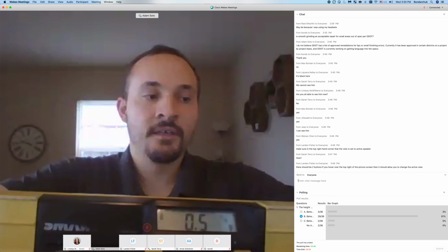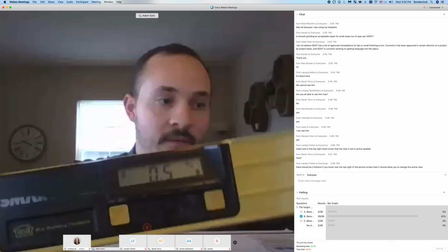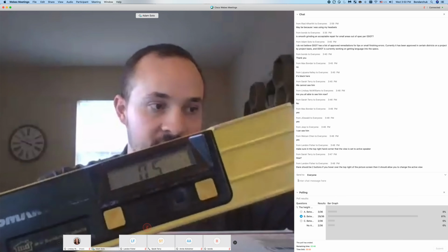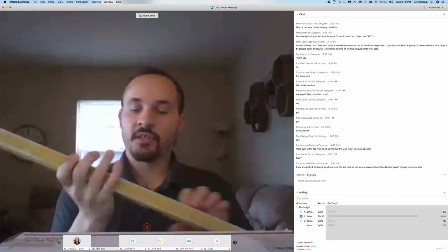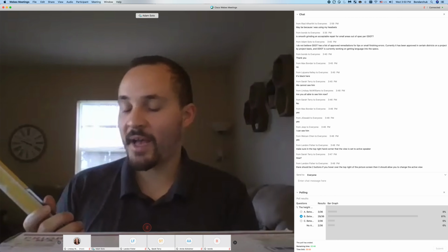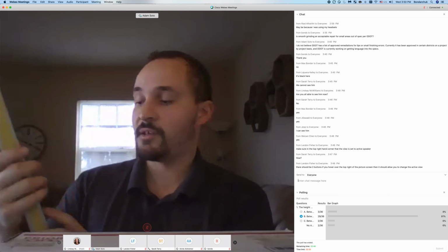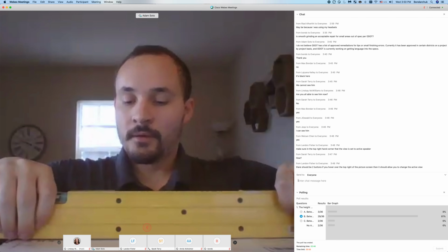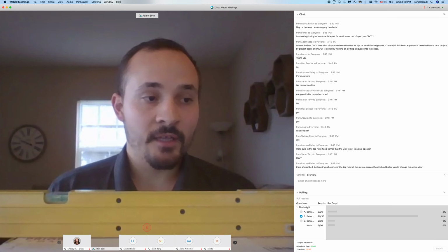As you can see, I locked the screen. So you can see, right now there's a screen lock function on the level, so it won't change. And that's what those arrows flashing on the side mean. So if you find that all of your ramps are passing at the same exact percentage slope, you might be locked on your level. But this level is calibrated.